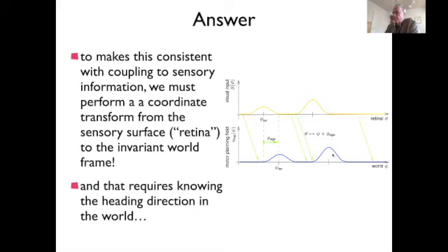But actually in the vehicle, it doesn't really matter that much, as long as you occasionally get some sensor information that resets where you think an object is. So if you have the wrong estimate of your heading, then you're just going to transform that input to a wrong value, but then you're also going to translate it to a wrong heading direction command for your motors, and so the error cancels. So the error shouldn't change too fast in time. That's the only problem.